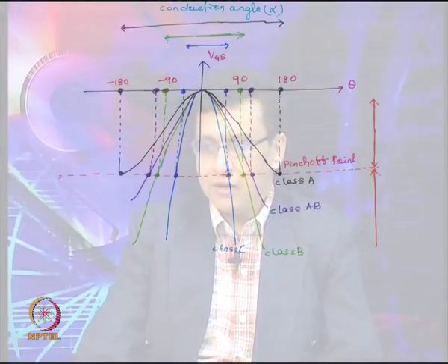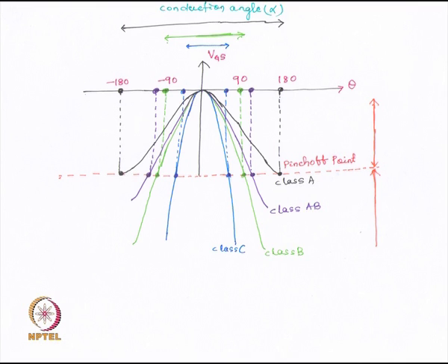If we want to ensure that, and at the same time we want higher efficiency, then we have to cut corners on the output current. So by compromising on the quality of the current output, we can ensure that the efficiency of the amplifier is high, while the voltage waveforms remain the same. Depending on this, certain classes of amplifiers have been formed.